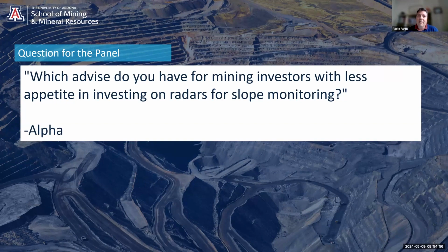So I think it's important to design the slope monitoring program in the right way, without shooting at the beginning when, from a geotechnical perspective, there are no expected challenges. So you can deal with prisms, total station, a few geotechnical sensors, and so on. And then, of course, be prepared, and also plan, for more complex monitoring systems, integrating one radar, more radars, InSAR as well, when the situation is different.